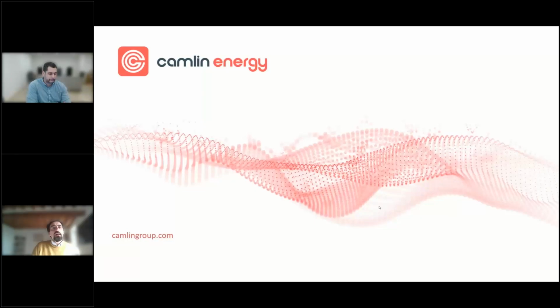Okay, thank you. Next question is about the sensors. Coupling capacitors is not the only available sensor. What about stator slot couplers? Okay. Yeah, so stator slot couplers are good in the sense that they provide a very well denoised signal just inherently.